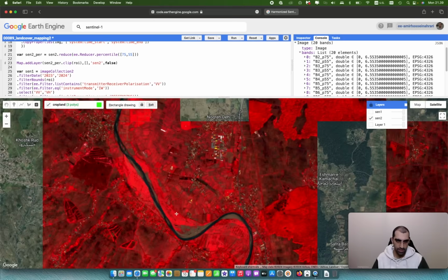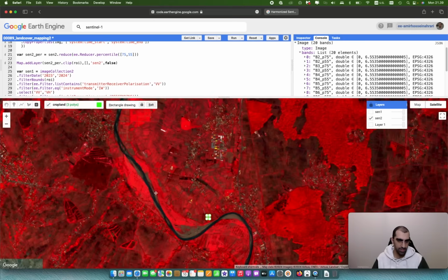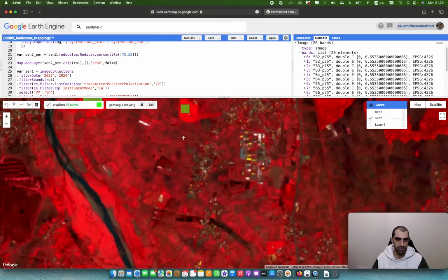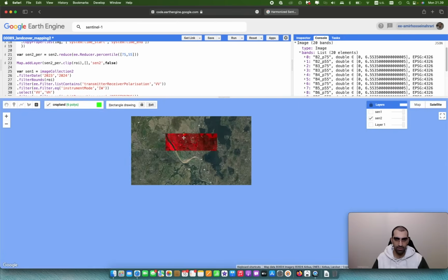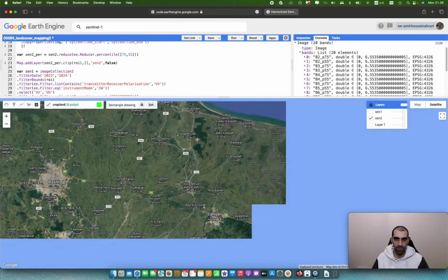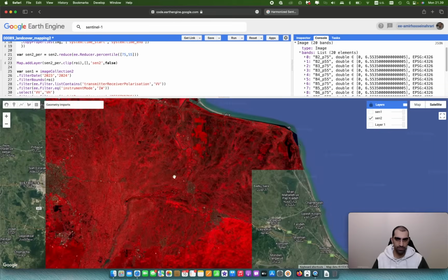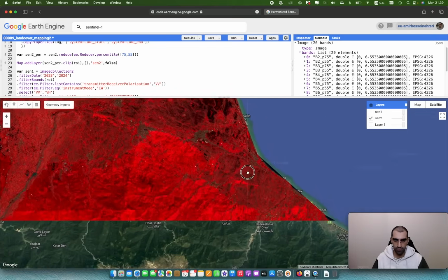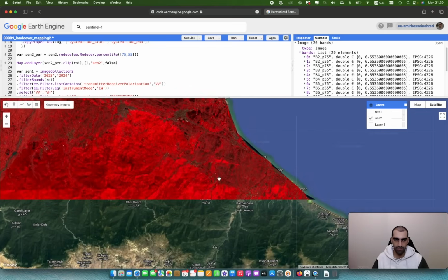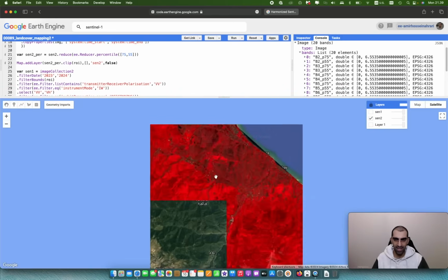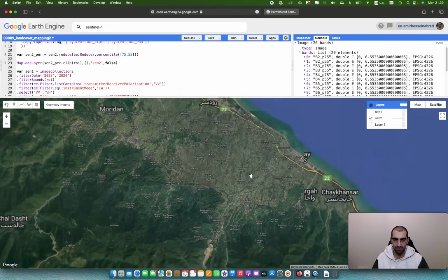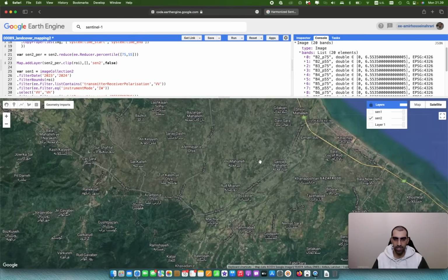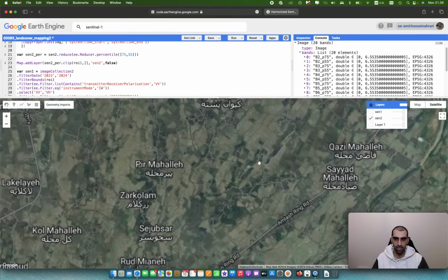So here, for example, I'm going to take some samples from this area, just like that, and then go a little further or scroll more on the images to find a newer area that may have different NDVI behavior during the time.